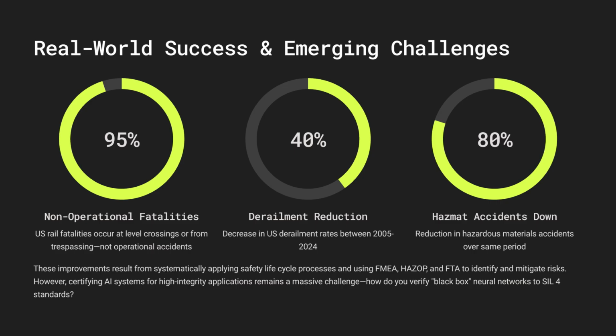Right. This is where the detailed FMECA thinking comes back in, considering factors beyond just pure mechanics or electronics, like the desert environment. Precisely. Extreme heat, pervasive fine dust, and sand. These things introduce failure modes you just don't encounter in, say, Europe. For example, standard smoke detectors in the stations. They'd be triggering false alarms constantly because of the heat and dust. Which could lead to people ignoring real alarms or disabling the system.